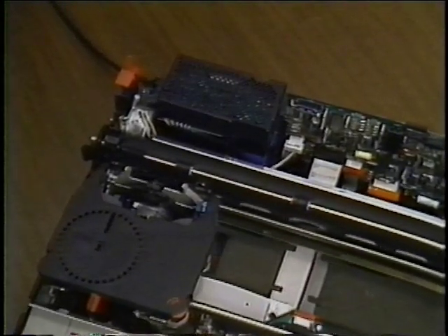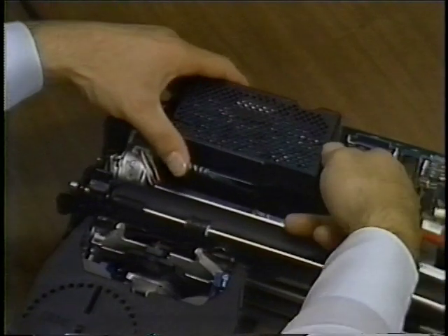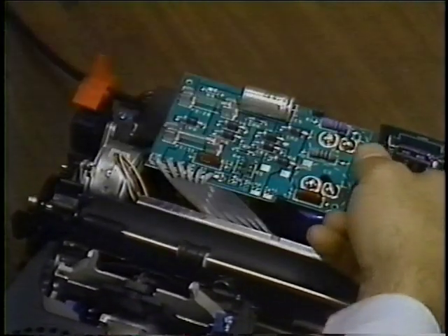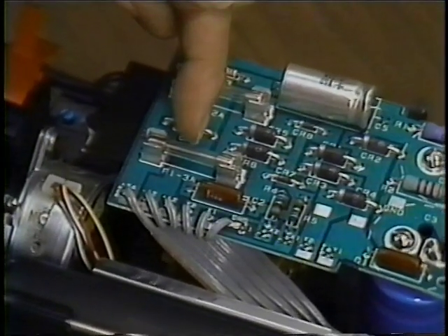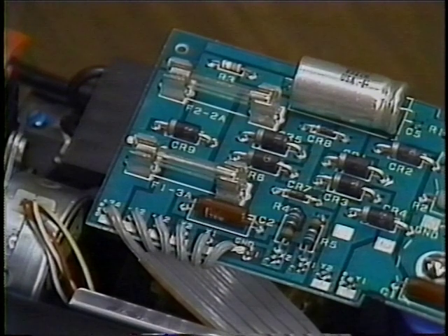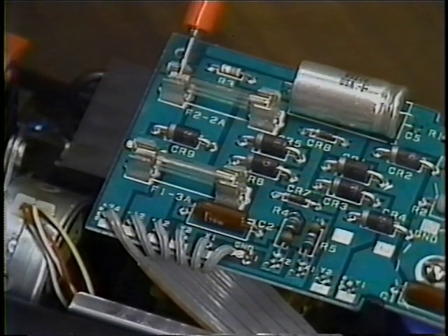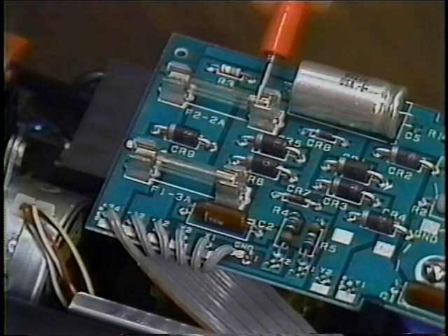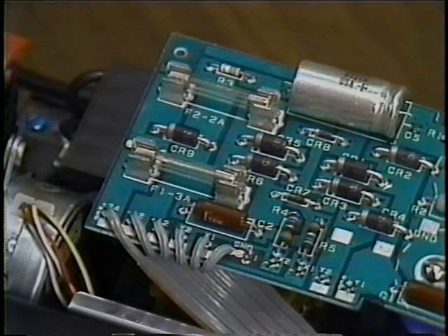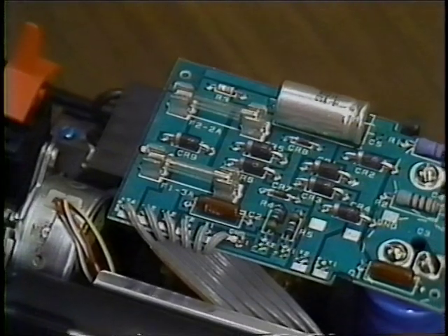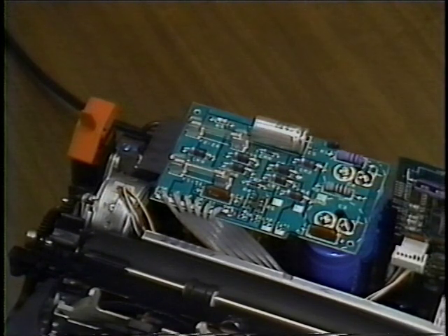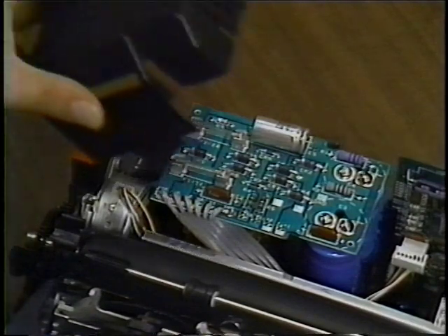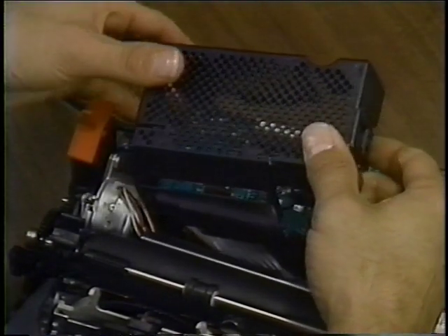There are 3 fuses in this machine. 2 of the fuses are on the rectifier board on the power supply. To get at these fuses, it is necessary to remove the power supply cover. To check a fuse, set your meter to measure 60 volts DC. Check for the same voltage on each side of the fuse. If the fuse is bad, you will read voltage on one side only. Always be sure the power has been off for at least 2 minutes before installing the power supply fuses. After checking the fuses, be sure to install the power supply cover.